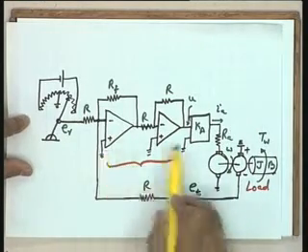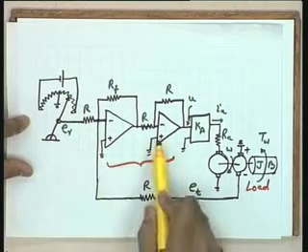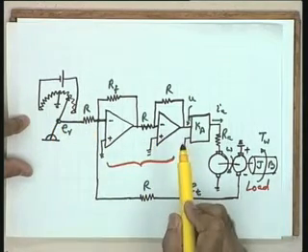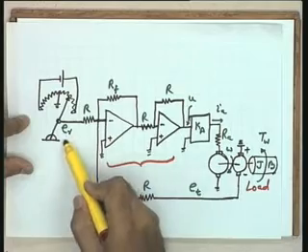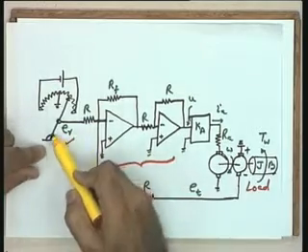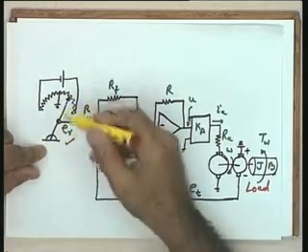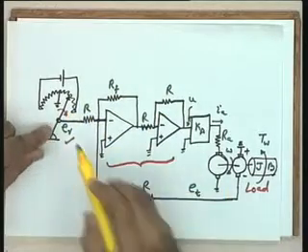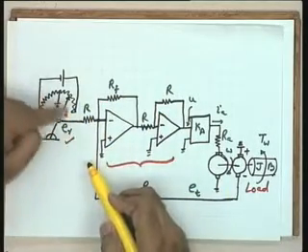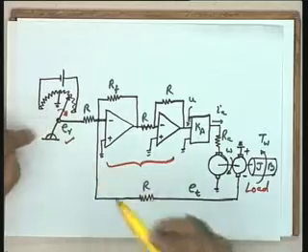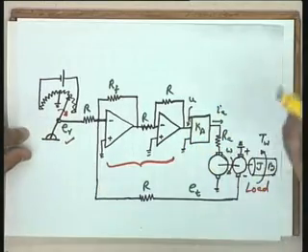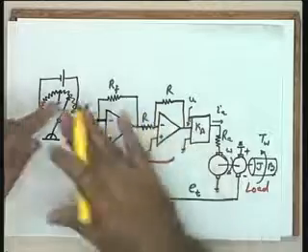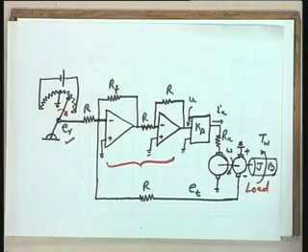So, you find that this amplifier is getting two signals. One is the reference signal, ER, please see, and this ER you are able to vary by varying the position of this wiper arm. So, you will change the position of the wiper arm with respect to your requirement on the commanded speed, omega r, in this case not explicitly shown.